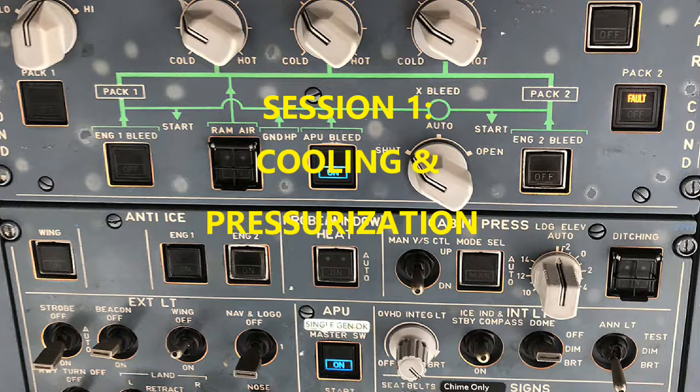So what about the power up test? That's the third test involved. The power up test: if the aircraft is on the ground and we're assuming the valves are closed and packs are switched off, and your pack controllers are energized and have finished their power up tests, then after about a 5-second delay, the zone controller power up test is done.